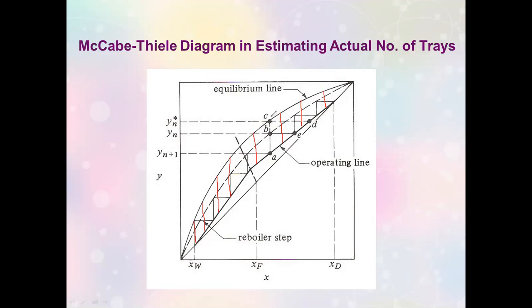That's very low, but just for illustration purposes. So you have a Murphree efficiency provided by the problem, which is 0.7. How will you now use that 0.7 in making this new curve that you have? What you will do is determine the length of the lines that you have here and multiply that by 0.7.